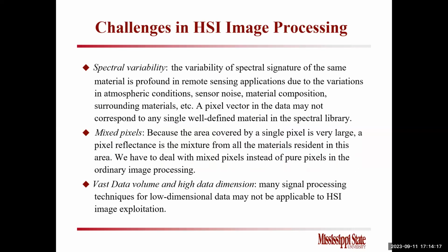Like spectral variability, I believe that is for all the remote sensing data. Because the signature in the library or the signature taken by the sensors could be different, directly using those deterministic approaches for comparison may not offer good performance. So we have to consider this variation by using some statistical approach.